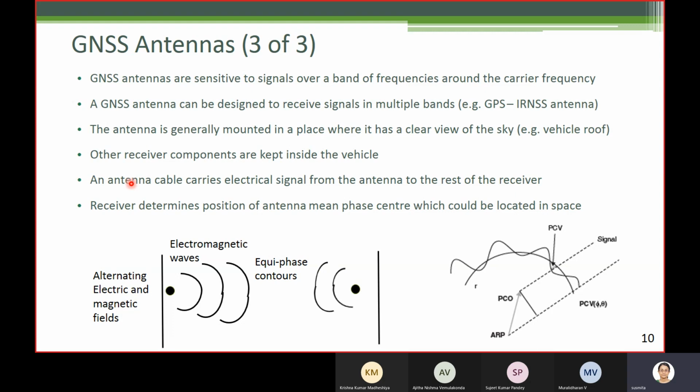So the cable length can be measured and the cable delay can be precisely obtained in advance. Then from the estimated receiver clock error, this cable delay component can be removed, and the remaining part can be used to correct the receiver clock. Without that, it will wrongly steer the receiver clock. So if the manufacturer opts for correcting the receiver clock based on the estimated clock error, he or she has to compensate for the cable delay.